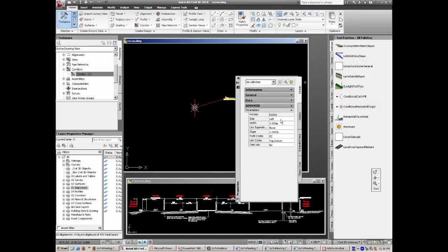So this is going to go to the left, and it's going to get a value of, we'll say, 1 meter. Again, that's going to be changed anyway. What I will do here is for my link codes, I will also call it landscape. If I want to build a surface model later on of just my landscape area, I can build model, select landscape, and that will work for me.